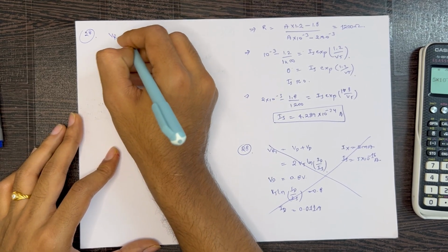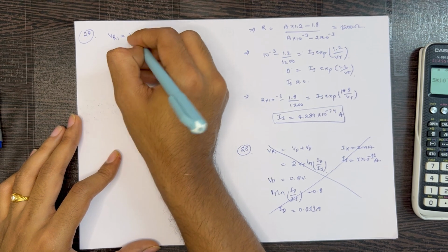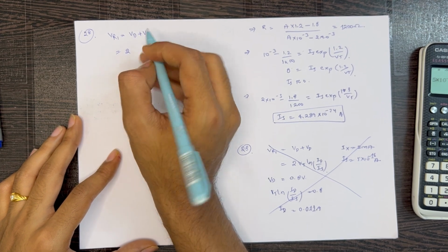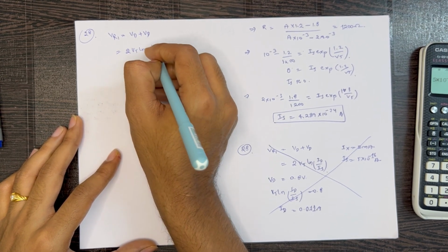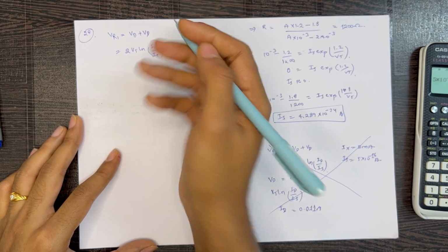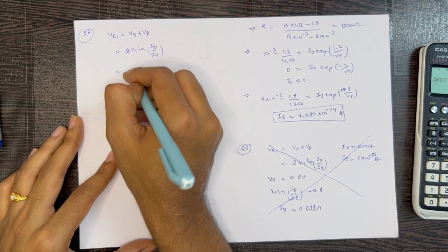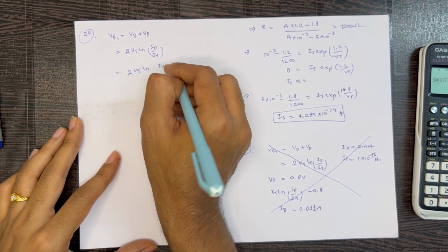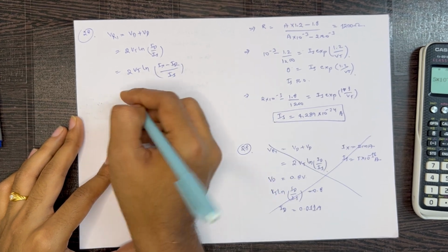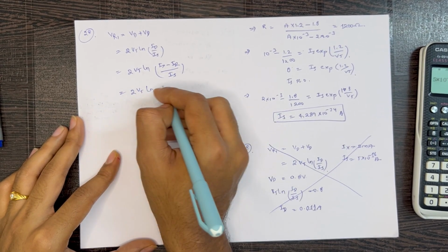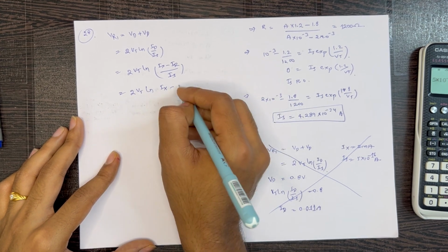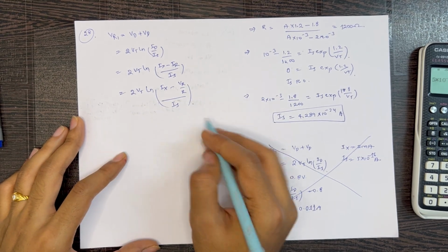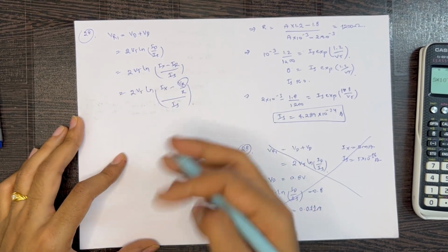So that is VR1 equals, it is basically Vd plus Vd. It's two identical diodes. So 2 times Vd, and the diode equation will be Vt ln Id by Is. We don't know Id, so we can write that as 2 Vt ln of Id as Ix minus Ir by Is, and that will be 2 Vt ln of Ix minus Ir as Vr by R by Is. R value is given, we need to find out R. So basically we have to do this iteratively.